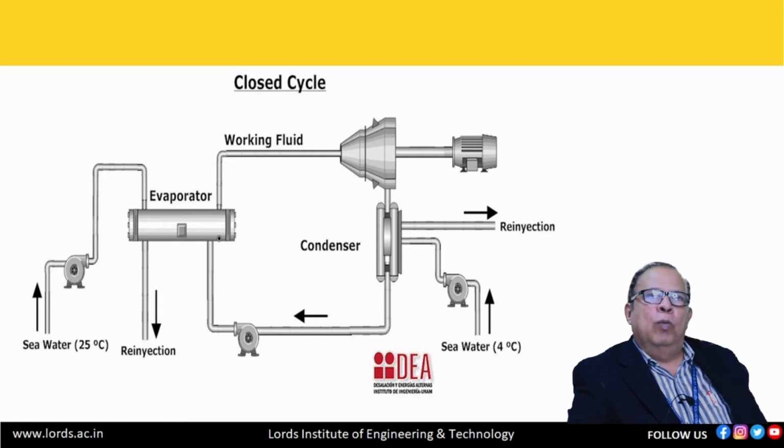Now one more fluid in the evaporator will be ammonia or some refrigerant, the working fluid. Because of the temperature of the water at 25 degrees, it will be able to boil the ammonia. So this ammonia will be evaporated and sent to the turbine, where the vapors of the ammonia will rotate the turbine, and we know that the turbine is connected to the generator to generate electrical power.